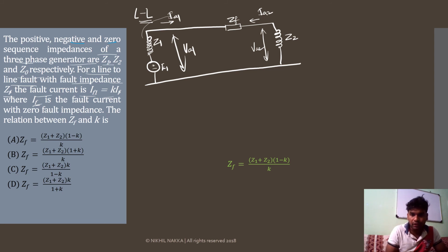And you see how the fault currents are included. So zero sequence current will be zero, but positive sequence current and negative sequence current are both equal and opposite to each other. So these are the relationships. I hope you remember these fundamental things. So from this we can write down the equation for this particular system.